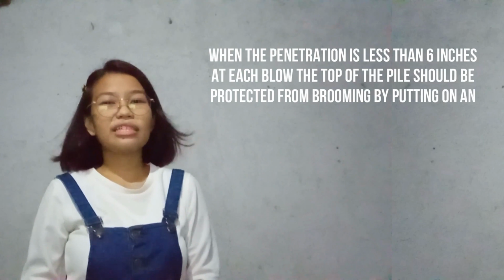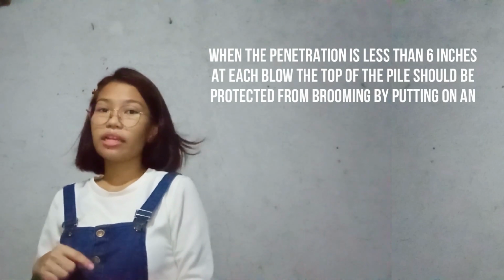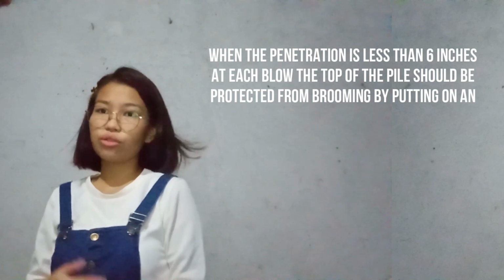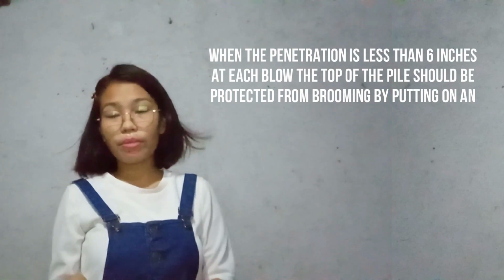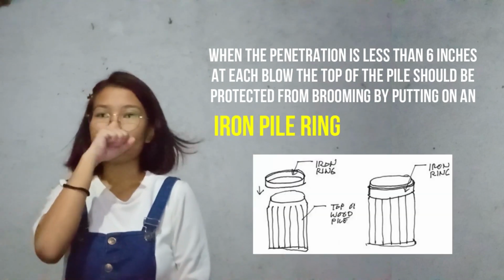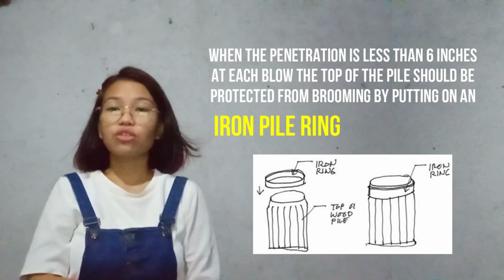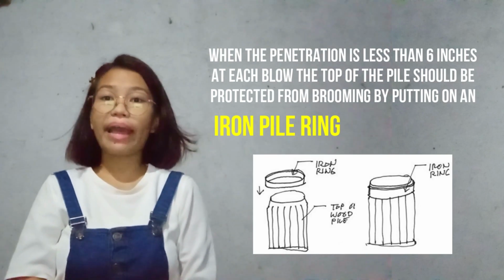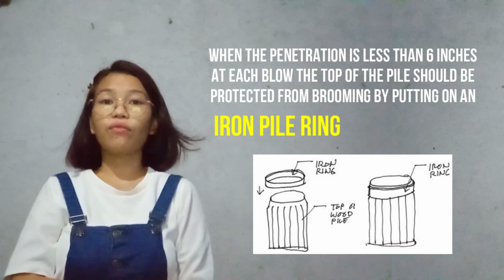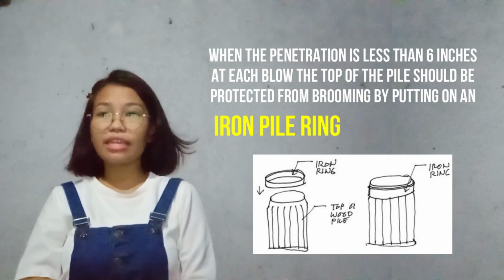When the penetration is less than 6 inches at each blow, the top of the pile should be protected from brooming by putting on an iron pile ring. A pile ring, also called a driving band, is a steel band which encircles the head of a timber pile to prevent it from splitting when being driven.